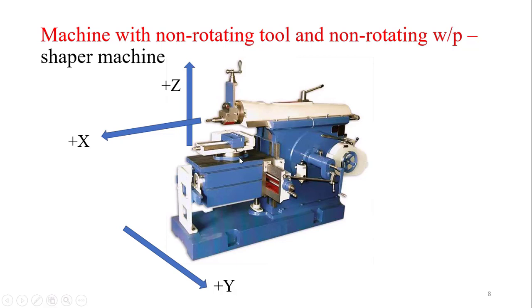So it is your holding surface. Okay. This is your holding, and it is the maximum size. First condition, it should be of longest distance. Fine. It should be horizontal. It is horizontal. Thirdly, it should be parallel to the holding surface of the workpiece. So the workpiece is held over here. It is parallel to the holding surface, and perpendicular to both x and z is y, positive. Right. So this is how we can define the x, y, and z axis in any CNC machine.